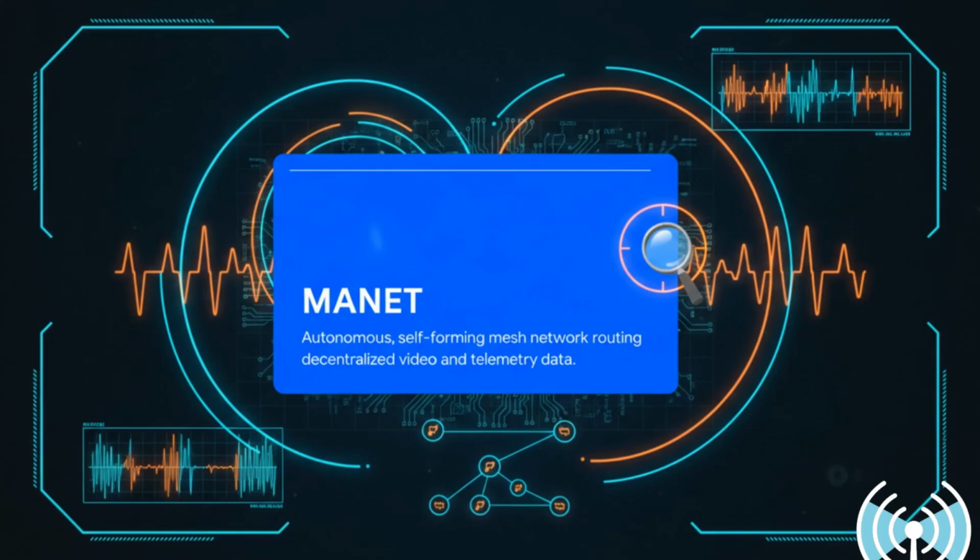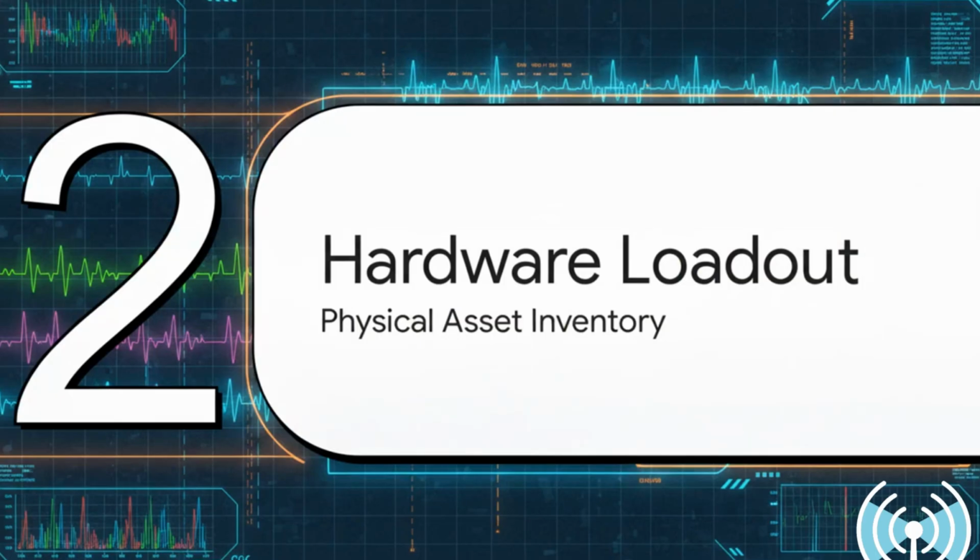It's totally autonomous, it's self-forming, and by utilizing a Zynq-7020 paired with an AD9363 Software-Defined Radio board, we're creating a tactical data unit, or TDU. This hardware becomes your backbone, routing decentralized video and data directly node to node. No central server required.